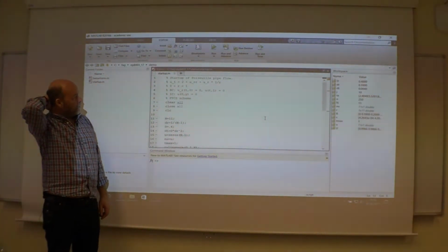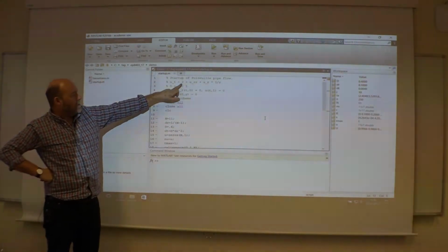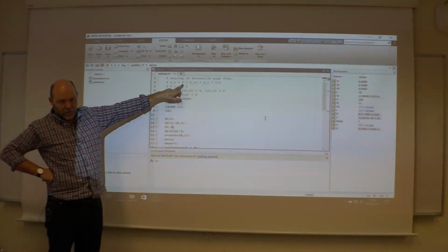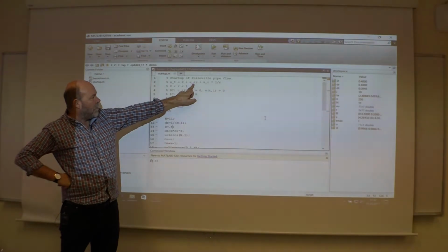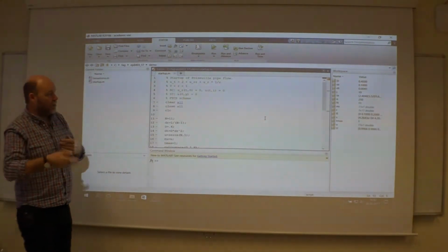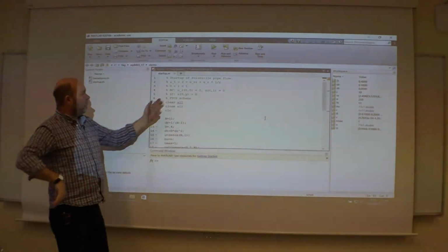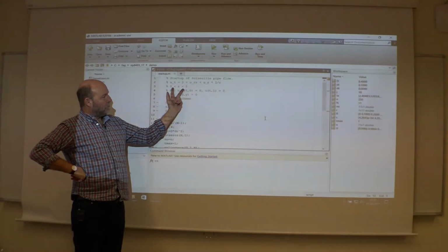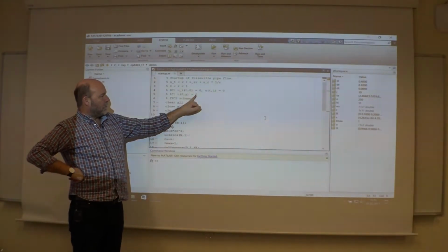Demonstration program, MATLAB. So the equation here, it's written in this non-dimensional form. The driving force constant equal to 2. Double derivative with respect to r, and then a single, and then 1 over r as well, due to these polar coordinates. My radius goes from 0 to 1, non-dimensionalized. Initial conditions, everything equal to 0.